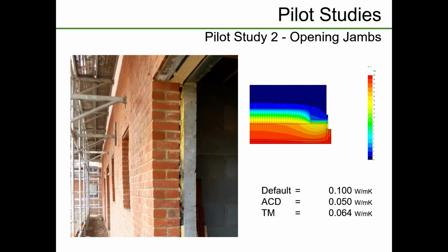Interestingly enough though, what you can see in this picture here is that there's a split lintel arrangement going on here. We've got a steel outer lintel and we've got another lintel inside here. They're two separate lintels. We've got partial fill cavity wall insulation here, and that's 100mm PIR in the cavity. You can see first of all it's not tight back against the inner leaf at that junction, and there's no cavity closer either. Okay, why not?